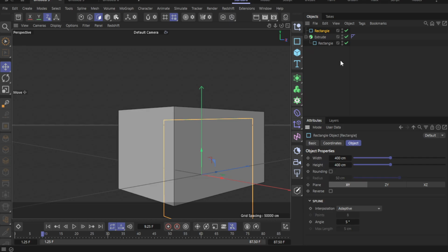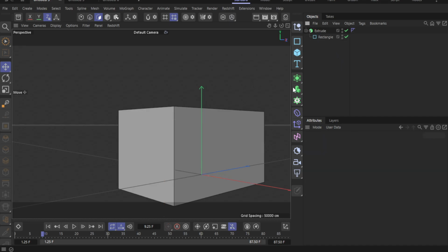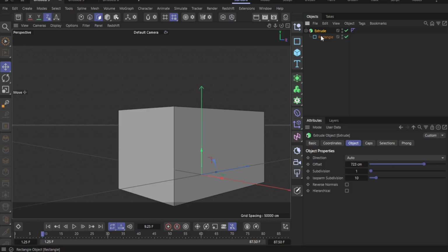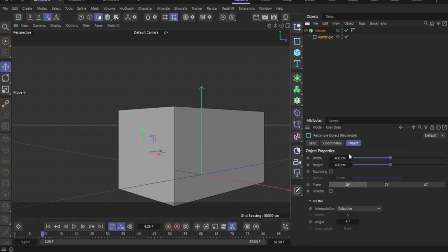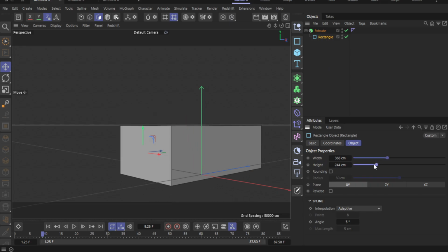That's the core workflow. Use the Extrude object with a spline for quick editable geometry, use the Extrude tool on selected components for targeted modeling, and choose MoGraph Extrude when you want flexibility and effects-driven control. Save your project, experiment with different offset values, and you'll be building clean extrusions in no time.